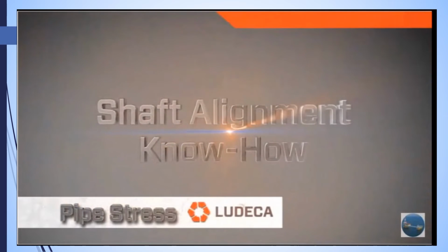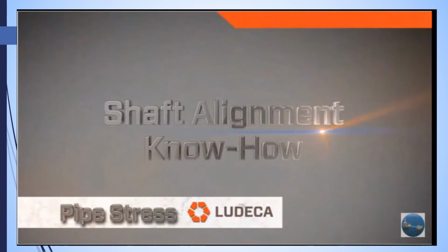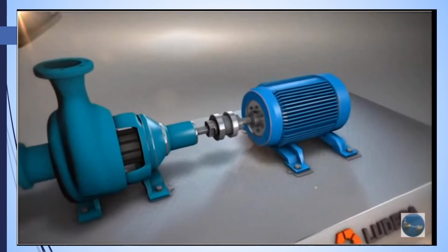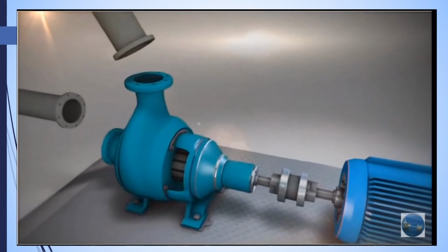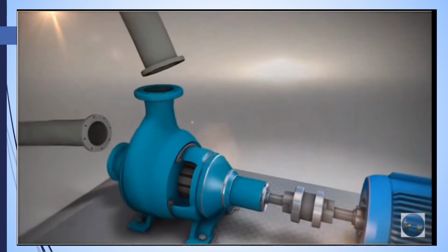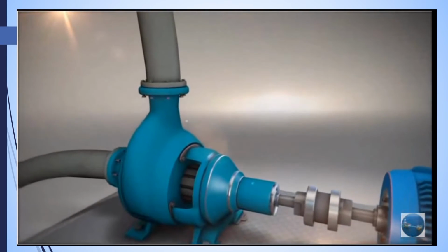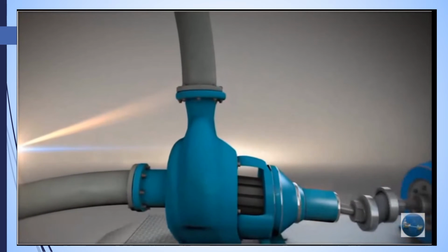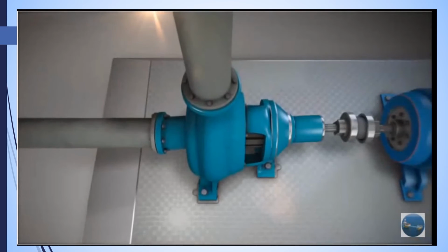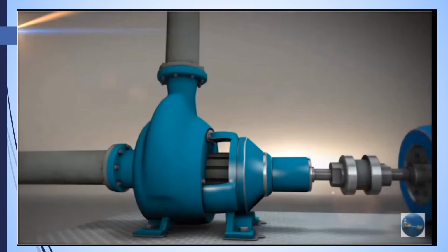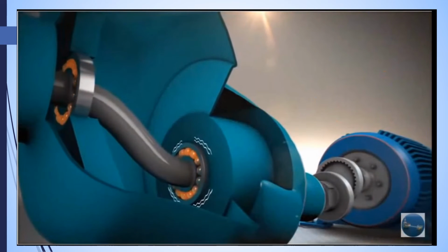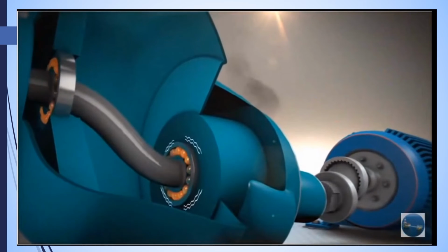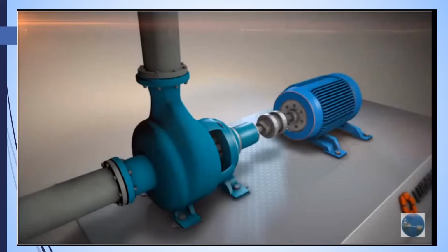Shaft alignment know-how: pipe stress. Often during pump installations, pipe and pump flanges are not in alignment. When mated together, the pipe stress pulls on the pump flange. This forces the frame of the pump to distort vertically and/or horizontally. The resulting deflection of the pump casing results in internal misalignment of the bearings, inducing vibration and premature failures.